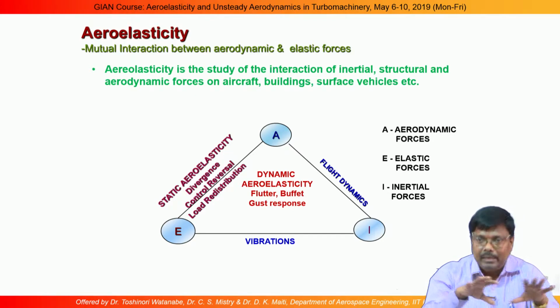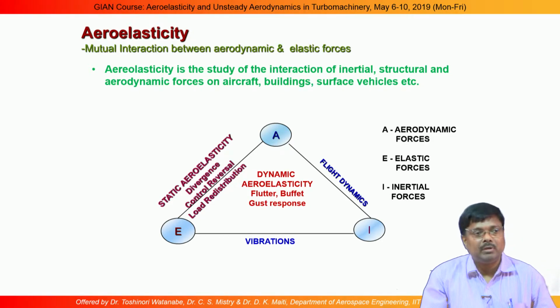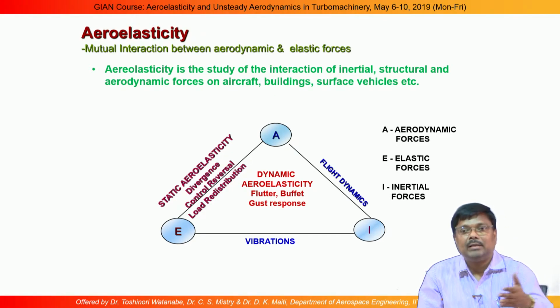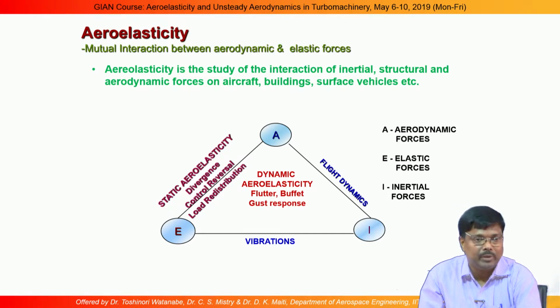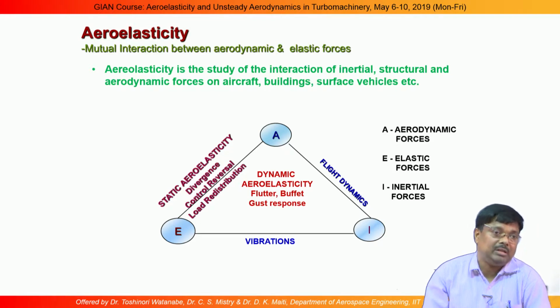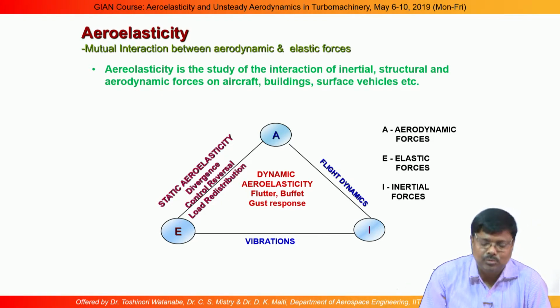If you have a tail wing construction in the aircraft, when air passes through the main wing, it is disturbed, a vortex is generated, and that hits the tail wing, at a particular angle of attack. That type of analysis we define by a term called buffet. In some types of aircraft it has to be designed so that it will not have any problem.